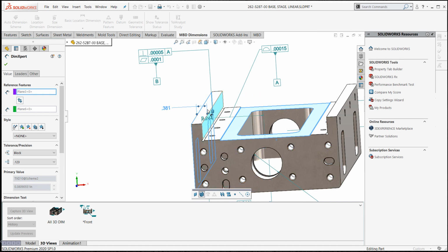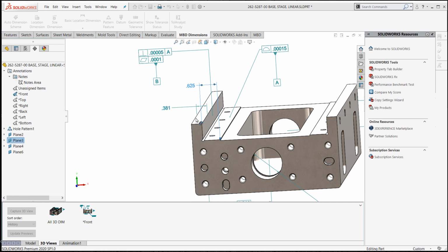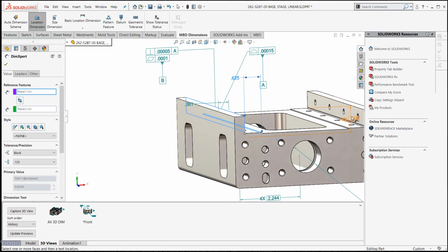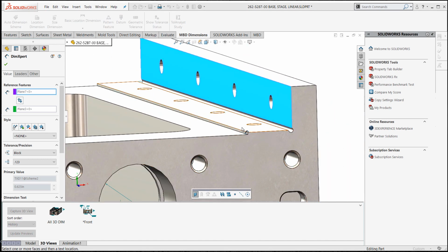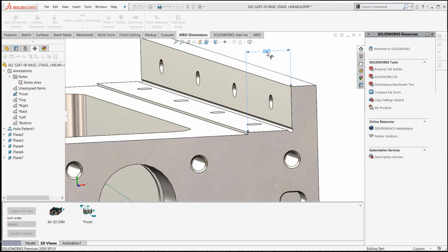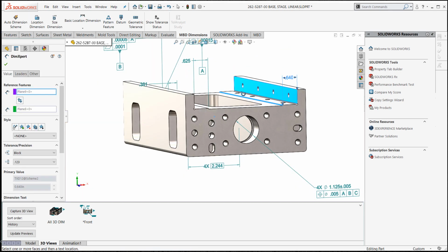So instead of going from this plane to that plane, it really took off and went to the center of the notch. Well, I can force that back on plane just by clicking there and plane, and then it's going to give you your normalized, from point to point dimension in there. So do a couple more of those. I'll go ahead and do one from here to here and try to get things going along a little quicker for you here. Let's kind of do a couple more.